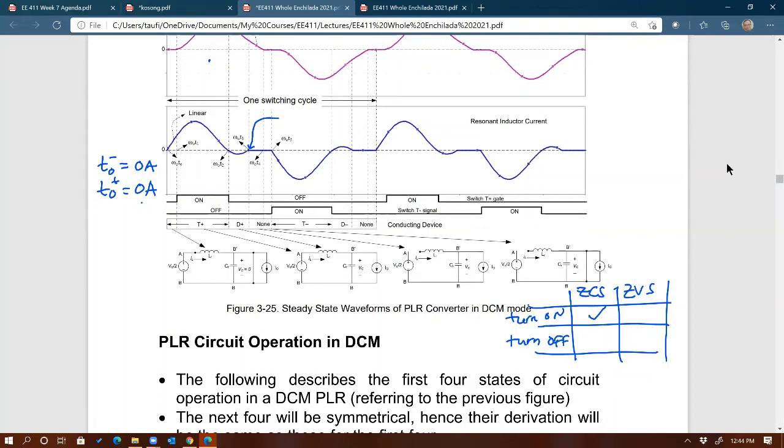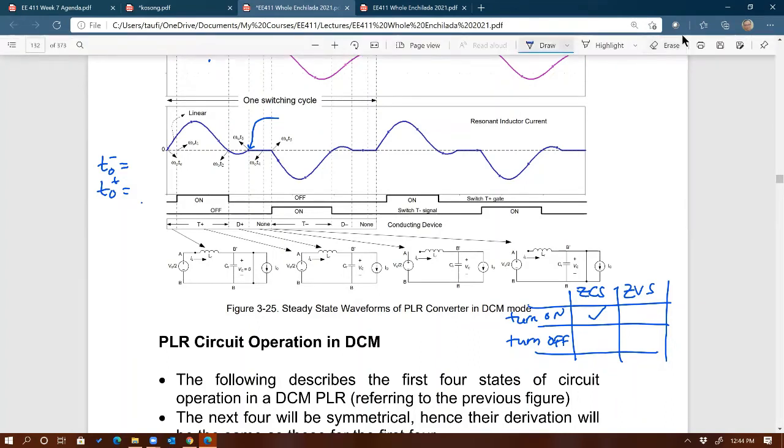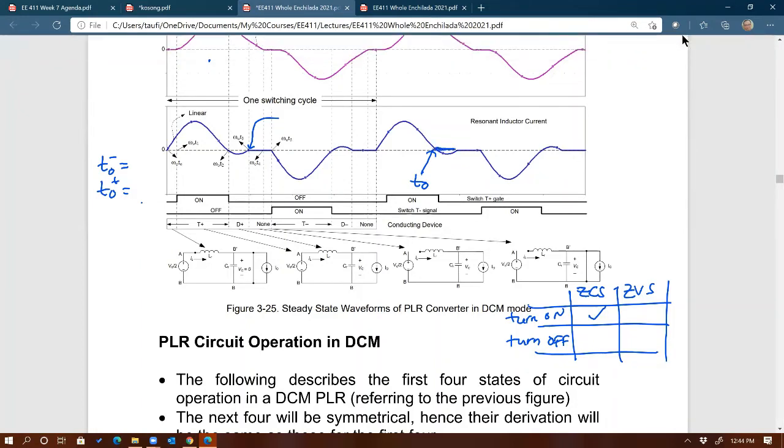Looking at the graph, the inductor's current is the same as the switch's current, and you have that little flat line after, which is at 0, and then you have a sinusoid before, which is basically 0. Yeah, very good, Nick. So T0 plus means right after we turn off the switch. If I call this T0 for turning off, then right after it's going to be flat, because it's off anyway. So we know that T0 plus must be 0 amps. That's the easy part.